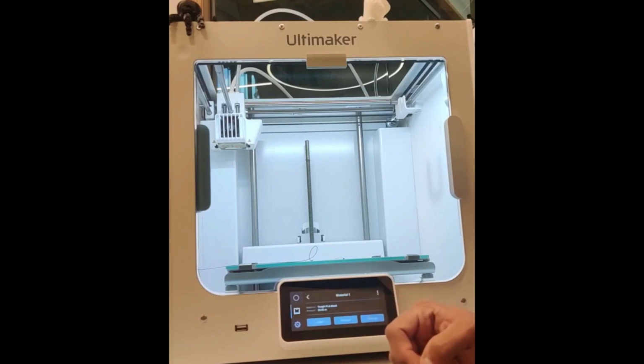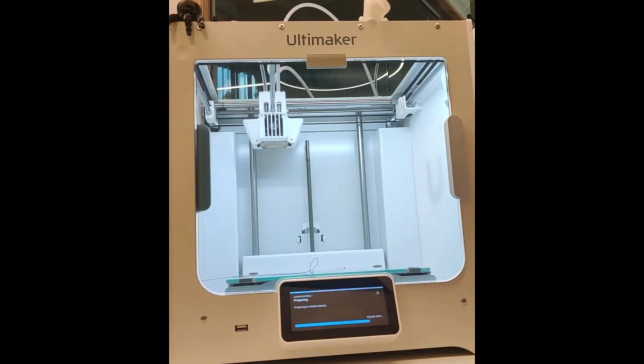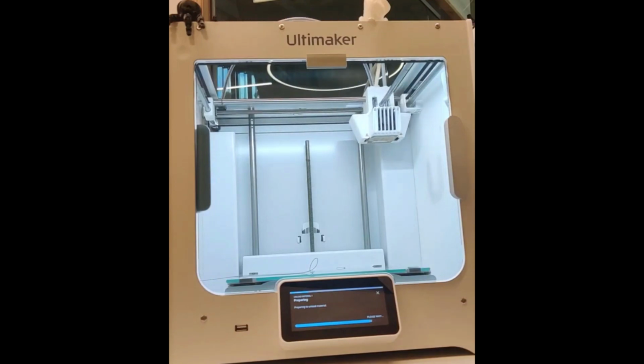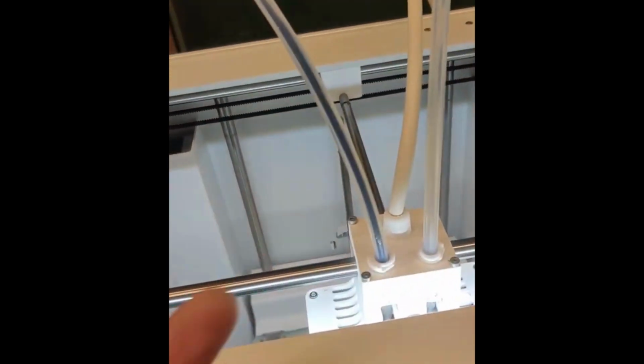So we'll select this Tough Black PLA, and then we have the options load, unload, and change. So we're gonna unload it and change it basically. So the instructions are actually the same. So first I'm gonna hit unload. And while that initializes, you'll see that the Ultimaker is doing a couple things. But this is Bay 1's, I guess, Mobius tube.